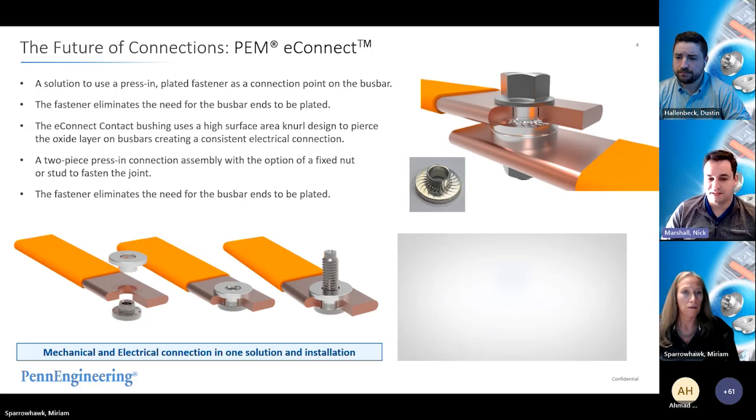When we install this into the bus bar, we have a series of ribs on the bottom of the head that you can see in the animation and in the image in the middle, which pierce into the top surface of that bus bar, breaking any oxidation layers and embedding the conductive element of the bushing into the bus bars. By doing this, we're able to create a very, very low resistance joint between our bushing and our bus bar.